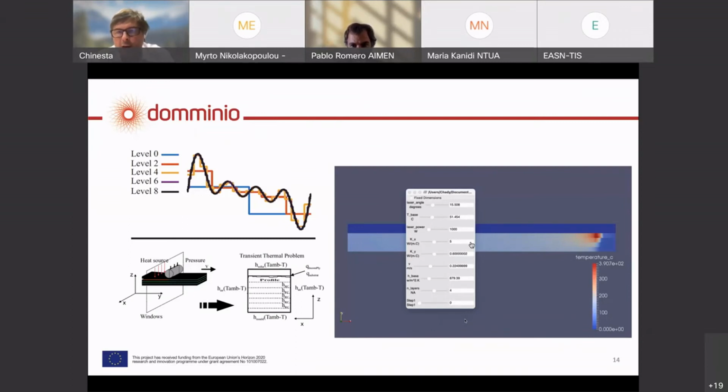And in order to take into account that we are applying the tape on something that is also a rough surface and the contact is not perfect, there are two parameters that describe the substrate, its temperature and the thermal resistance that, for example, is infinite. This means that the heat cannot move to the substrate. So depending on the quality of the substrate and depending on the contact between the tape and the substrate, we can adjust this parameter H that is controlling the thermal heating.